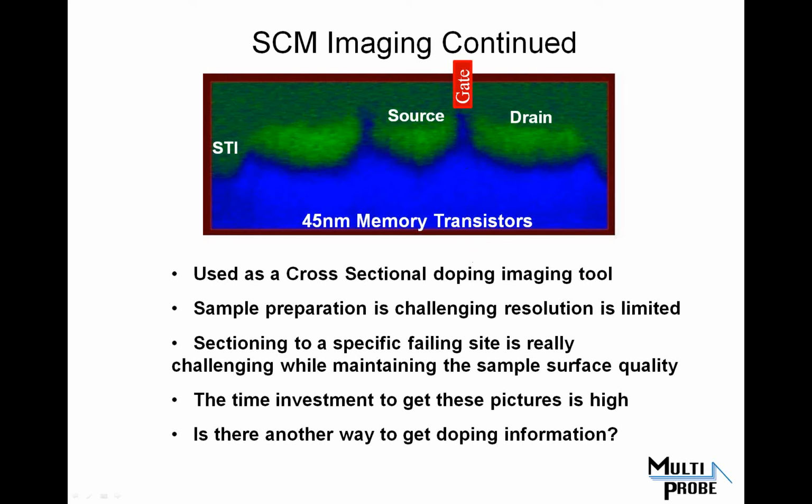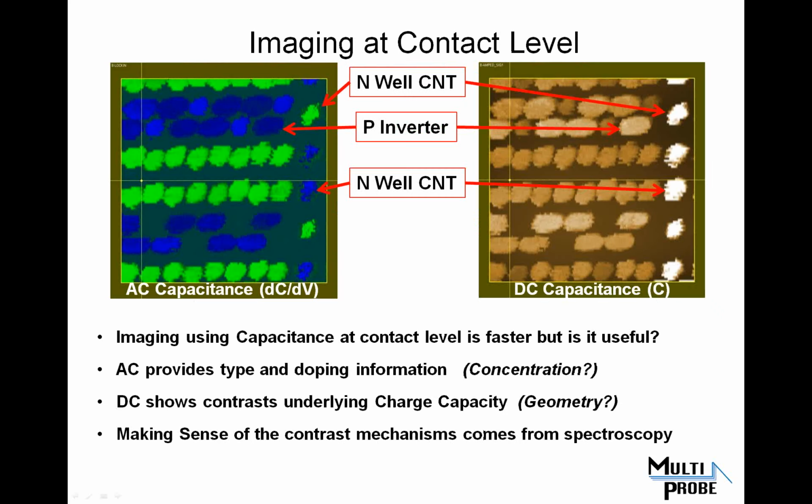At the imaging at contact level, I can tell you that it certainly scales down to 22 and probably below that. So at contact level, the nice thing is the capacitances that you end up measuring are really one of the constants in the scaling equation. So even as you shrink the gate length or the depth of an implant, you change the actual charge stored in that implant or in that gate, or you maintain that by changing doping or thinning oxides, and so that's a constant. So there isn't a limit in terms of doing the measurements at contact level and doing CV curves.